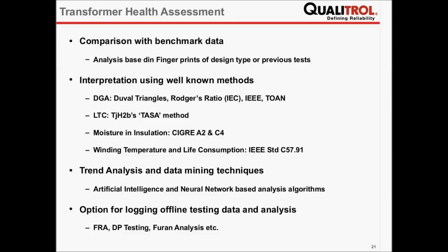Coming to the transformer health assessment, as I explained, comparison with benchmark data. The system should have a facility to compare or to do a fingerprint analysis, either using design type data or using the previous test. Interpreting using well-known methods, for example, this should have all the available well-known methods for dissolved gas analysis, for LTC monitoring, moisture in insulation monitoring, winding temperature, lifetime consumption, and insulation aging. So all sorts of models should be available in such a system.